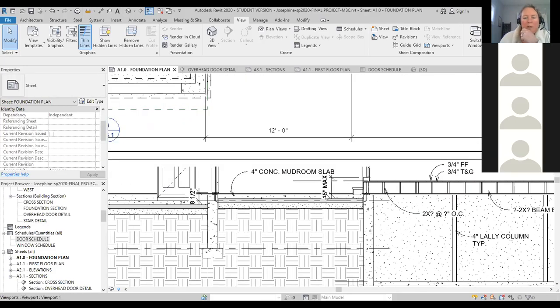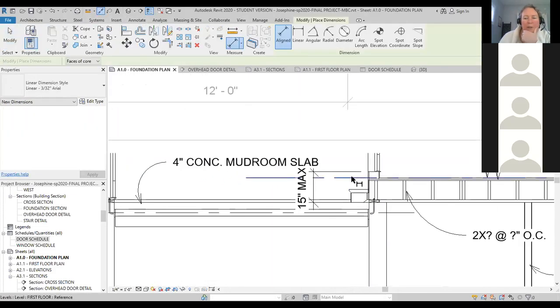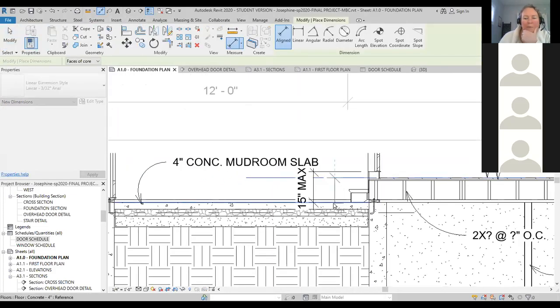From the first floor, I'll put the actual dimension here that I ended up putting in. I ended up putting the slab for that mudroom area at 1 foot 2 1/4 inches down, so that it matched the height of the top of the concrete wall. So that slab's being poured right at the top of the concrete wall. But I just put in here a variable to give a little bit of wiggle room for somebody who might be placing the slab.